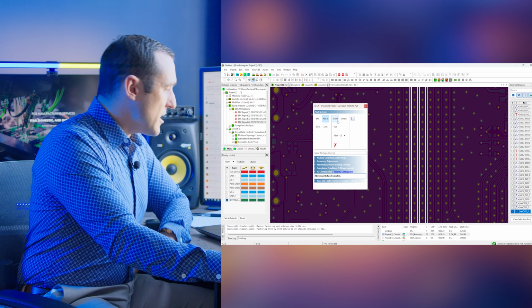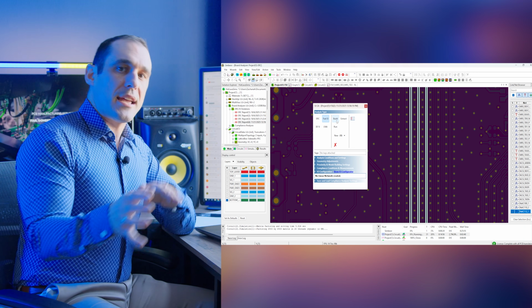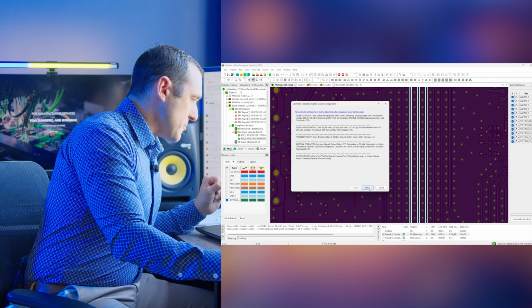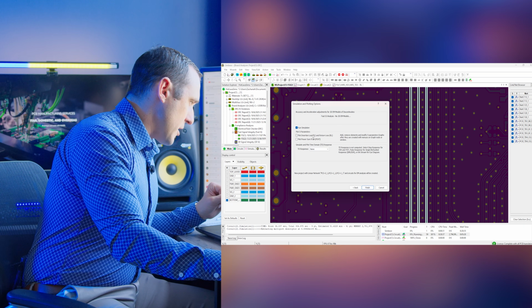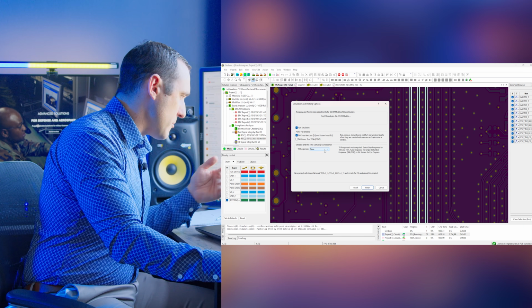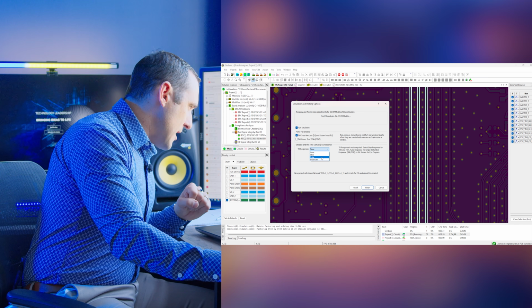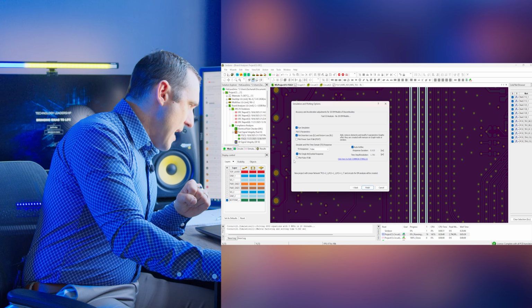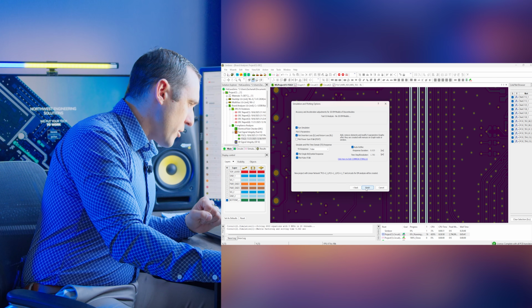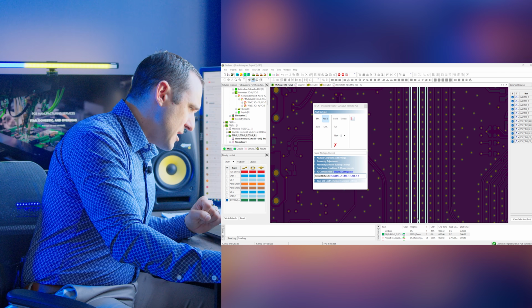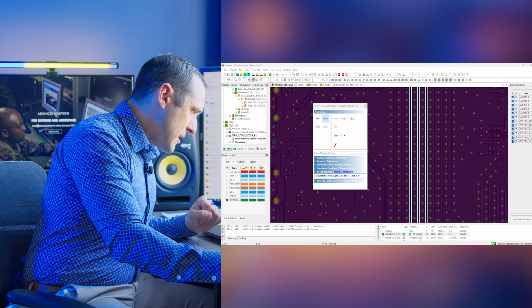So just as an example with these 3 interconnects, let's go ahead and build an SI simulation and check out the S parameters for these interconnects. A few moments later. In order to set up this model, we're just going to click the extract button. We're going to select what we want to look at in terms of the S parameters. Here we want the insertion loss and return loss. We're going to look at pulse time domain response, and we might as well plot the pulse crosstalk while we're at it. And we're just going to go ahead and hit finish. And you can see here it goes through and it's running, and it's going to take a minute to finish. We'll come back when it gets done.